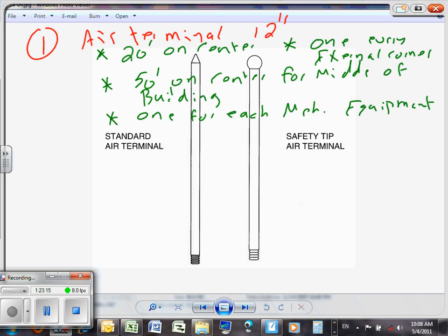We do have a Revit family. Please go to the industrial project, load the Revit family. Most of you guys I have helped with it, and you are there. Okay? So here's Revit-wise. What you're going to do, guys, load the family, drop the family like we did yesterday on the parameters, every 20 feet.